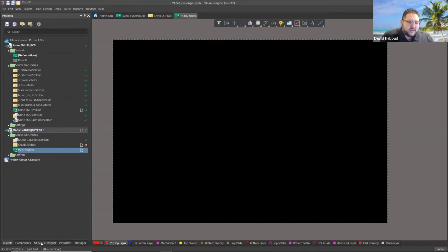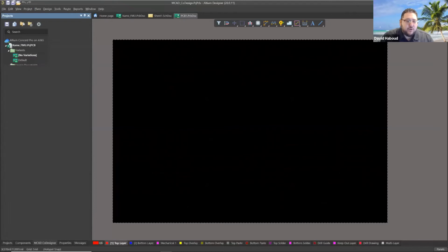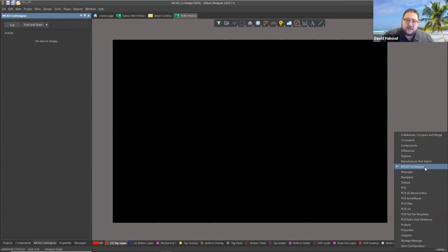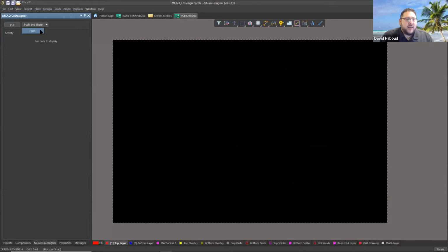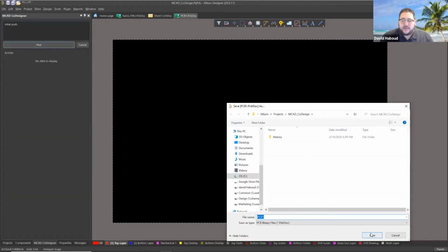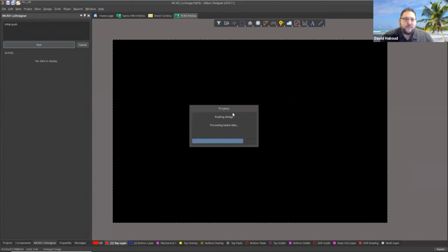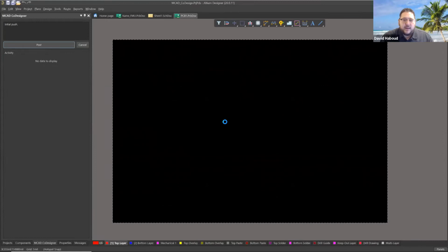Now that we have that done, I come over to the MCAD CoDesigner panel. You can go to Panels, MCAD CoDesigner if you don't have it up already. I'm just going to do push. If I do push and share, I can specify someone's email that I want to share that design to. But I don't want to send it to anyone, so I'm just going to say initial push. I'm going to post this. Of course, I have to save it for the first time.